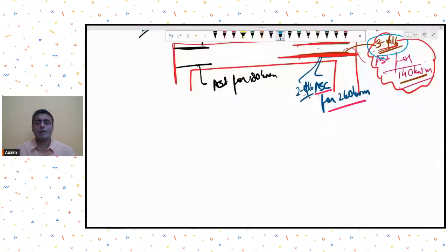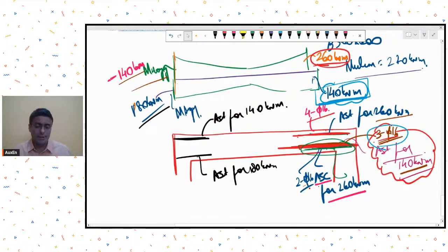that in such a case, if the compression bar has been provided over here because it was a case of doubly reinforced section, then you have to be careful about the curtailment length. You don't decide the curtailment length accordingly, depending on the bending moment diagram and its requirement. Also, be very careful about the development length or anchorage length that you need to provide at the ends. Be careful about those things.